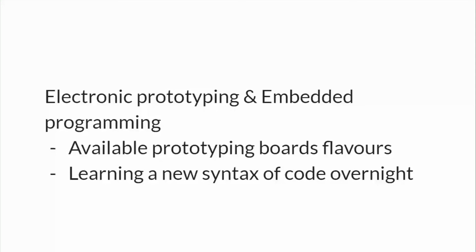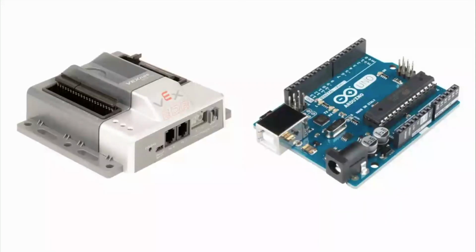Okay, next please. Now, in comparison, this is the Arduino Genuino Uno, and we have the VEX on the left side. They are completely similar, but the VEX uses a higher-end microcontroller which has many other peripherals like USB, but they function the same. They have the very same GPIO numbers and the same analog inputs, but they also have something additional, which is the motor controller driver on board. That would shrink the size of the electronic circuit. So we went for the VEX for faster prototyping. Move to the next.